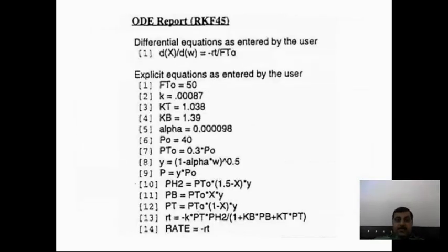So this is where we have everything ready. We have a differential equation, we have a rate law. In the rate law, we have pressure terms. The pressure terms were represented in terms of conversion. We have a pressure drop parameter for the packed bed, which is also given in terms of weight and alpha. All the explicit equations are well defined to support the differential equation.